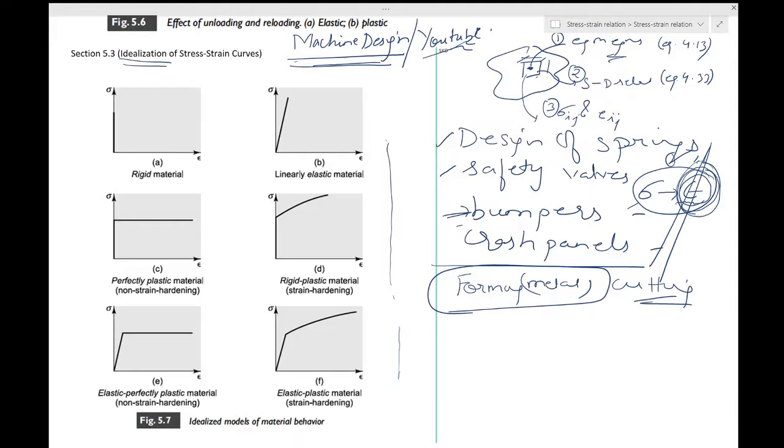So in metal forming, you should look and see if there's a risk of spring back, just like the paper you had would unfold itself. That is a problem because you don't want that to happen in a metal forming process. In metal cutting, the strains may be even greater than unity, and there is a plastic process where the strains are so high that there is plasticity and failure happens, and then you are able to cut the material and the chips are taken away. That's how you use mechanics in the material process. So please check the metal cutting process as well.